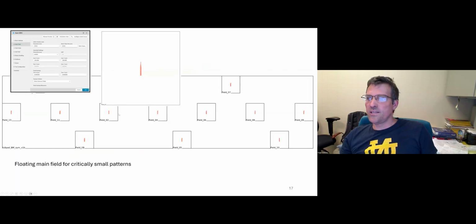So what you can actually do is reduce your field size, which is what I did in this other exposure where I had even smaller samples. For reference, this is a 50 nanometer line for a few microns, and the whole thing is about 10 micron long with 2 micron width. Obviously, this narrow region is the most critical part of this exposure. So what I did is I set up the main field size to be 150 microns. I know that this is a smaller distance than any of the pitch in these devices, and so the system is kind of forced with this floating setting to be around one device.